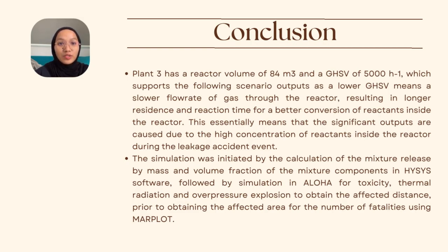The simulation was initiated by the calculation of the mixture release by mass and volume fraction of the mixture components in HYSYS software, followed by simulation in Aloha for toxicity, thermal radiation and overpressure explosion to obtain the affected distance prior to obtaining the affected area for the number of fatalities using MAPLOT.